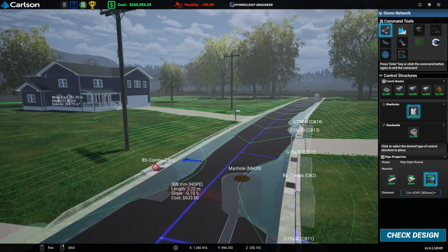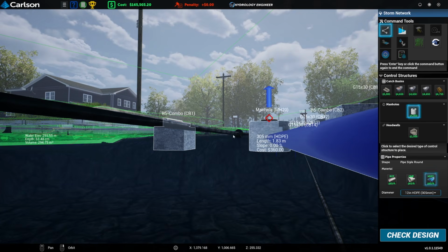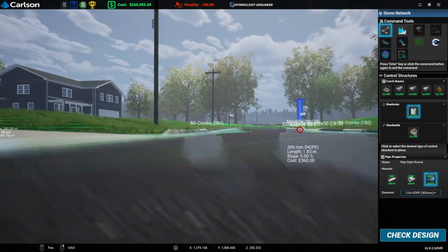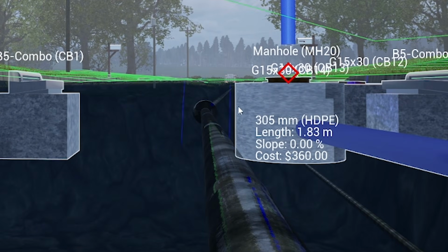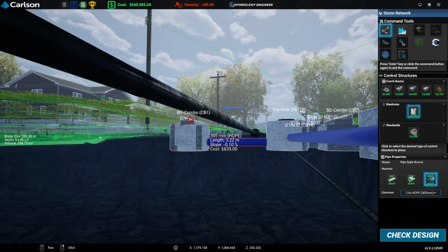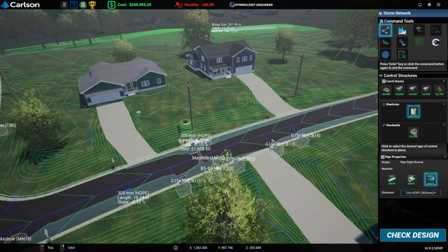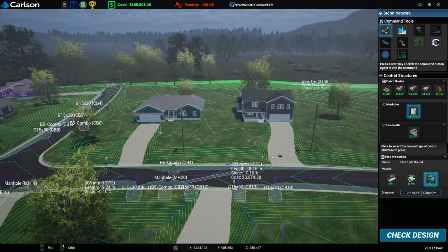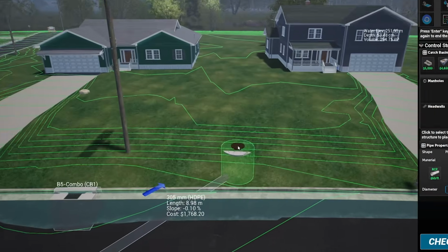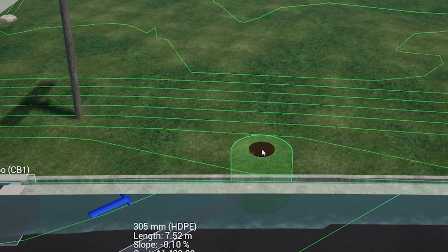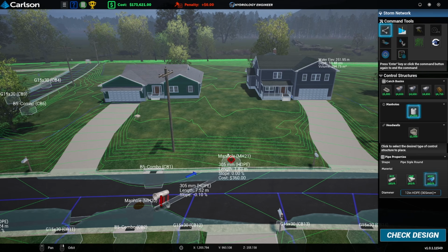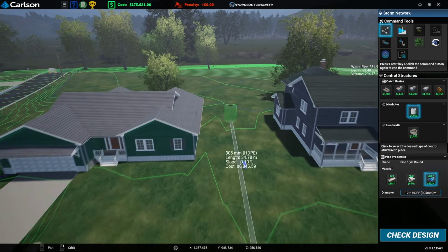And then if I just look underground, yeah, there's a water main through the middle there. So our manhole does miss that, so that's fine. But getting a pipe to go over this direction, we're going to have to be probably a little bit deeper than we currently are. So something to consider. But yeah, I think let's take a manhole, shove it there. You see down there the warning has appeared, but we will be adjusting the levels, don't worry.